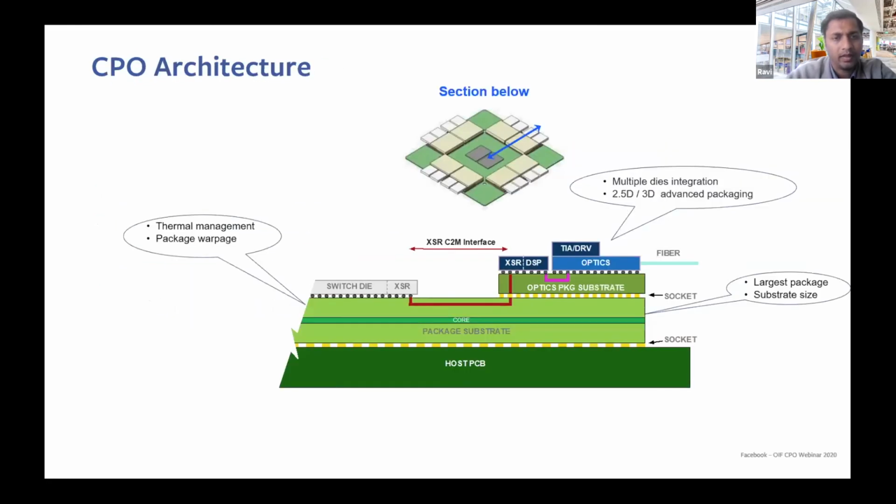So this is a schematic of a co-package system, which you can see on the top has a switch package in the center and 8 optical modules surrounding the switch package. And both the switch and optical packages will be mounted on a common substrate. And I want to highlight some of the challenges to make such a package in future, especially for this community, which can appreciate some of the challenges we will see here.